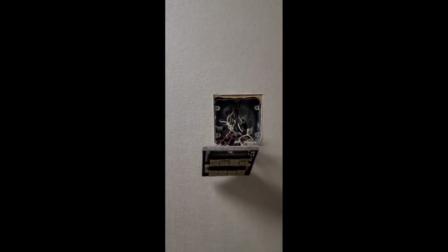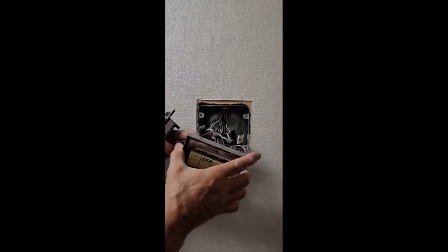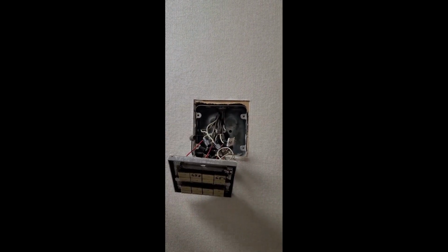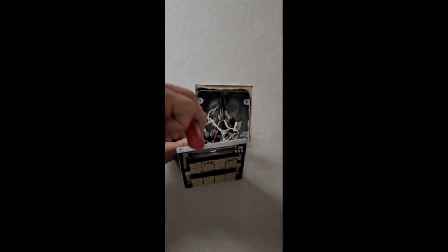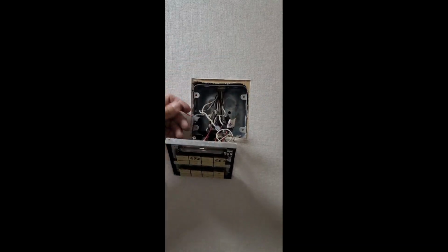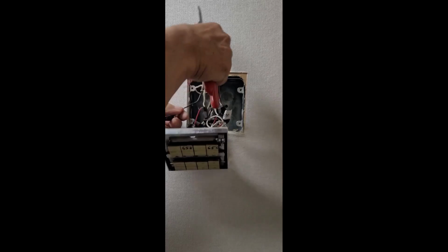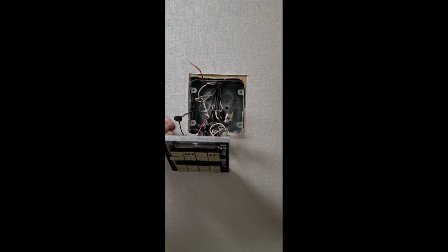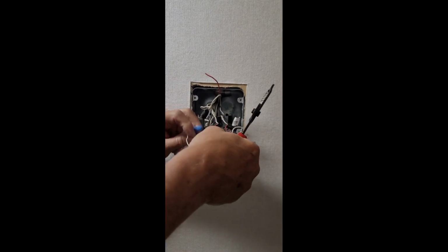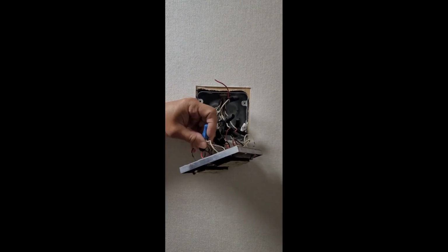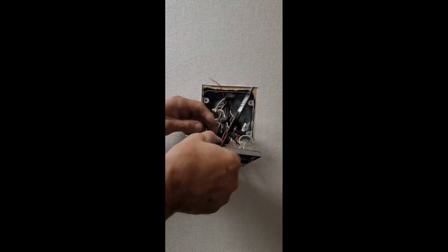Because the other end is where we do in the room. So in this case, it's the first switch. Number 1 switch, right? This side's up, number 1 switch. Cut the red one off. So that one there was the common to it. You don't care anymore. There's no more wire to it, right?